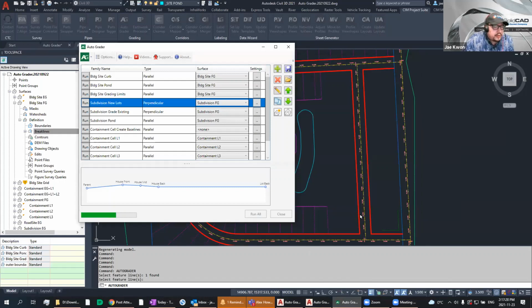And basically starting from that right away, every 25 meters is going to generate those side lot lines. And I do have the option to generate the back line as well, to just connect from point to point at the end of what I create, which is what's been done there. So that's a magenta line. So that basically created a bunch of new lots very quickly.